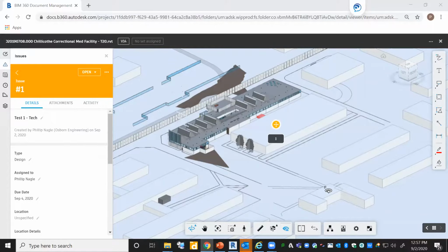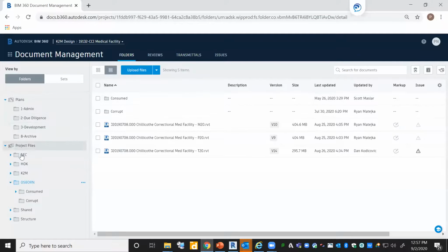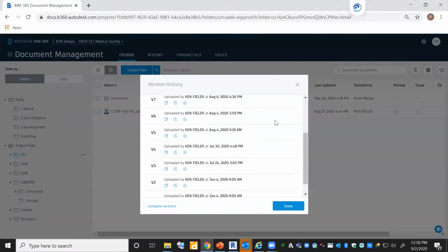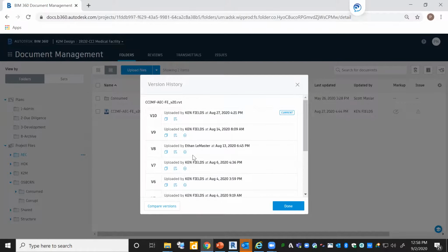No, not really. But like I said, anytime you do an upload or a publish, it does create a record that you can go back to later on BIM 360. In fact, the reason why it's able to do those compares, where it tells you what's new and what's been deleted since the last time it was published, is because it saves these older versions.